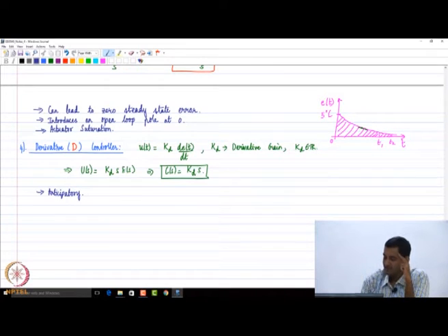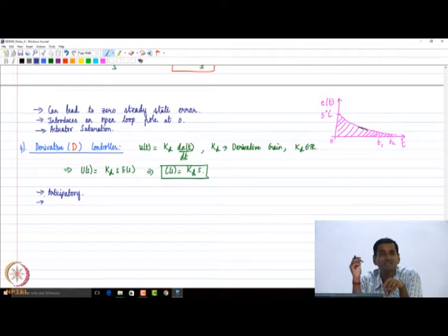More importantly, those are all important aspects. As he told, if you have a constant error, the derivative controller will not take any action, or will take negligible action. The error may not exactly remain constant, but if it essentially hangs around a constant value, the derivative controller may not be able to take sufficient action. And if you have a sudden change in the error, not even a discontinuity, due to whatever reason, the derivative controller may give very high inputs, which may be beyond the actuator's limits.